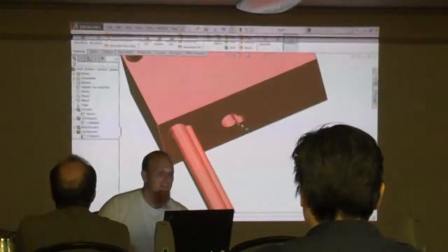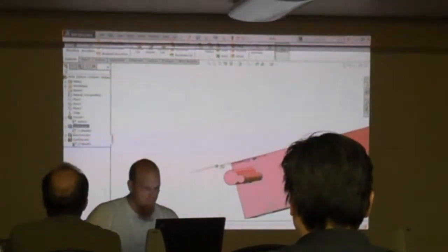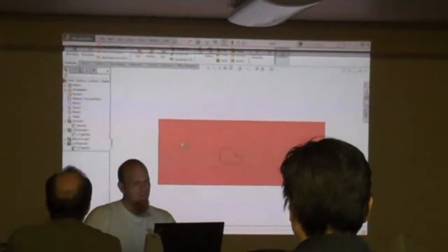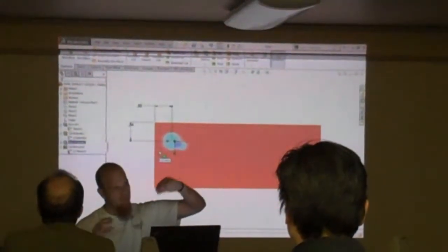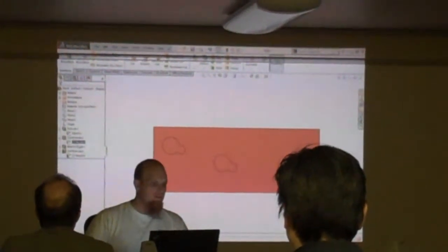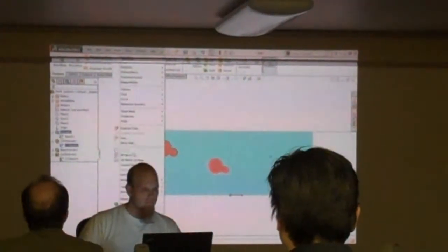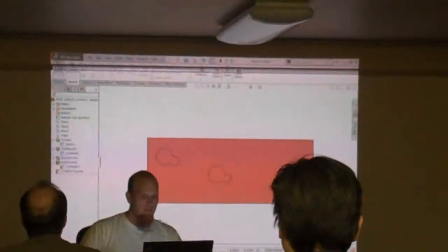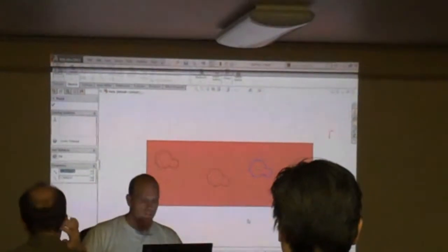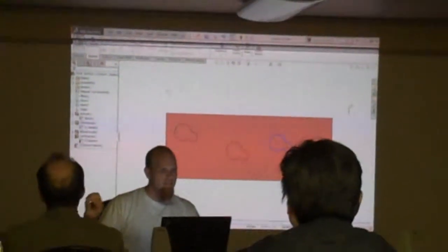Okay. One last thing on this, since I got some other geometry with it. These are all going the same way. Okay? What if one needed to be clocked at another angle or something like that? One last tool, and then I'll end this. Insert Derived Sketch. One of SolidWorks' very first tools. I've been using this since SolidWorks 96.